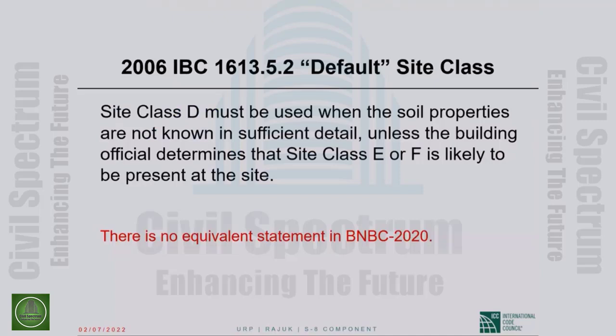Now, site class determination we will not talk about, but it is based on measured properties of the soils at the site. And ASCE 7 very specifically says the top 100 feet of the site, 30 point some meters. Okay.